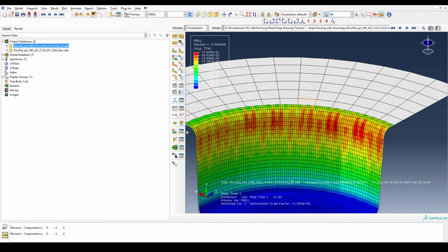You apply some compressive stresses because your ring segments are forced to move to a smaller radius. So this induces compressive stresses in the meridional direction. I don't know if that's the correct term.